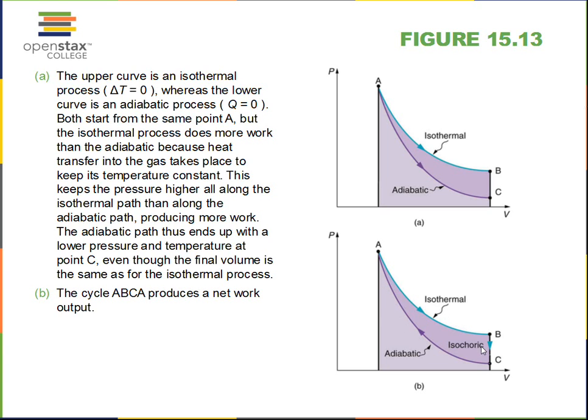And we have a situation here that the delta U will be positive. Delta U is Q minus W. We're compressing the gas, so work is a negative number, and the delta U will be a positive number. The gas is picking up energy, and that might be reasonable to you. It's moving away from the cold corner of the PV diagram, indicating that there's more energy in the system.